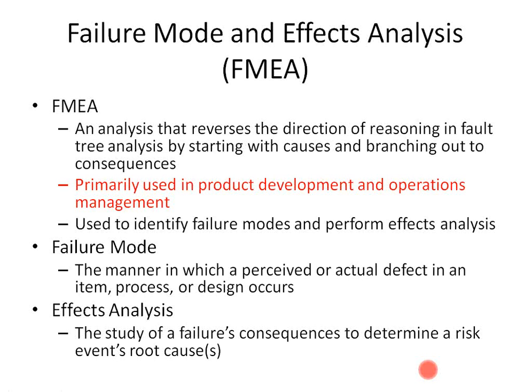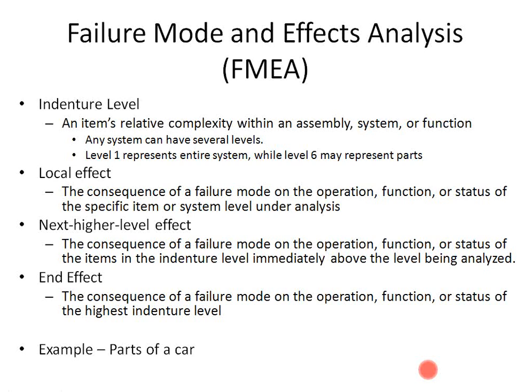So when we look at all these different techniques, there'll be a question of which one will be used for which purpose. This one is in product development and operations management. And again, it's used to identify failure modes and perform effects analysis, and obviously that's where it gets its name. So what's the failure mode? It's the manner in which a perceived or actual defect of an item, process, or design occurs. Again, what's the failure of an O-ring? Whereas the effects analysis, you say, okay, we look at the failure's consequences. We want to find out, based upon this failure mode, what are the consequences of this one piece failing, and that's what it looks at.